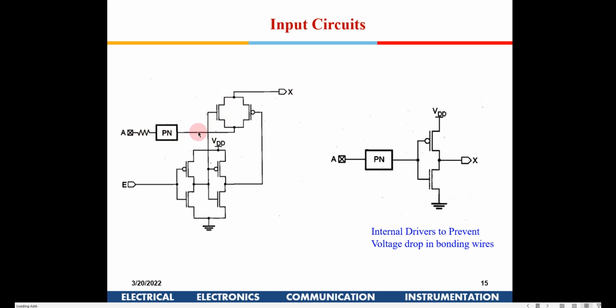So you see here that the output pin is not constantly connected to your circuit, only on a requirement basis, whenever there is a requirement, so that will protect your circuit, right? Only during that small window of operation, whenever you need to take an input, this transmission gate is enabled and the input signal is coupled in.